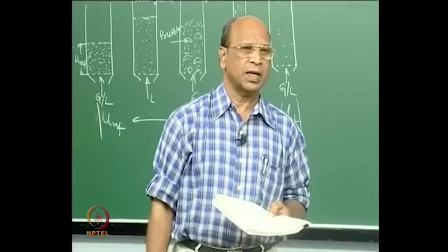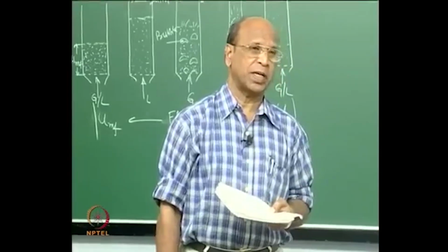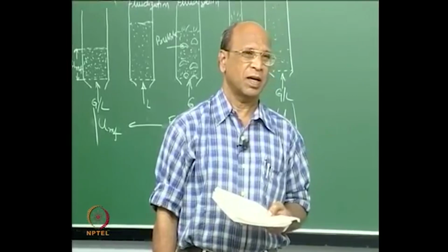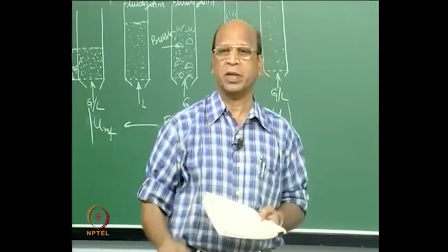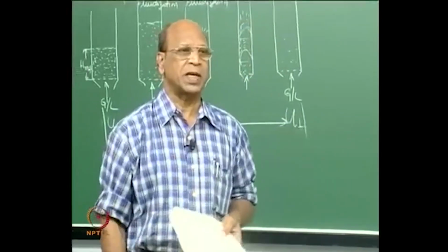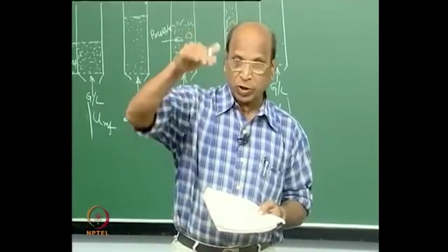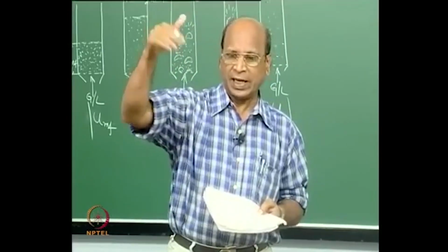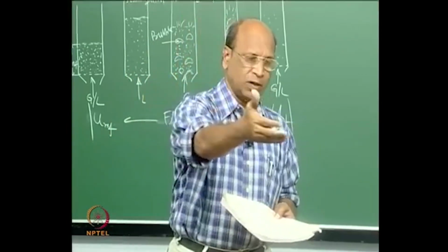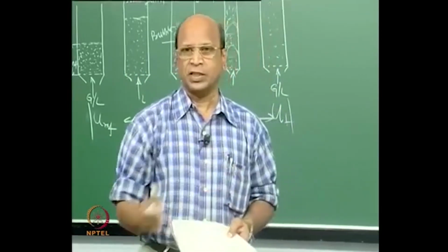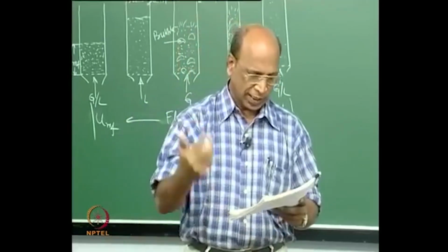Anurag, any other? Why is the pressure drop in the bed high? In a packed bed, what is happening? In fact, a packed bed gives you more pressure drop than a fluidized bed. So, pressure drop is not a problem, because if you are using the same velocities, like 2.5 times the minimum fluidization velocity, the pressure drop in the packed bed will be much more than in a fluidized bed. Pressure drop is not the disadvantage. So, anything else?